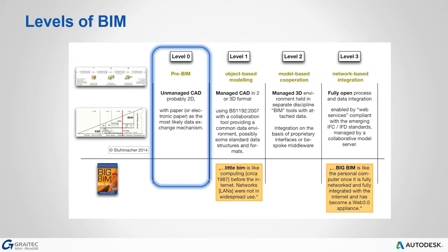First of all, we have level 0 BIM. This is in its simplest form. Level 0 effectively means no collaboration, no data collaboration. 2D CAD drafting is all that's utilized, mainly for production information, and this equates to RIBA's Plan of Work 2013 Stage 4. Output and distribution at this level is via paper or electronic prints, or PDFs, and probably a mixture